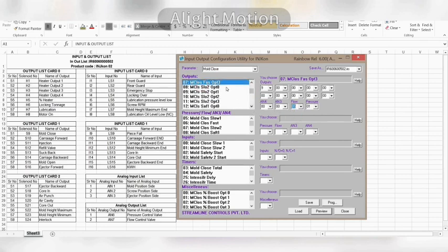Accordingly, mold close slow 2 option 0: output number 9 and pressure 0 1 and flow 0 1 enable. Same way, mold close slow 2 options 1, 2 and 3: output number 9 and pressure 0 1 and flow 0 1 enable in each.